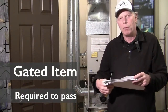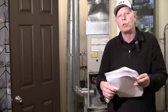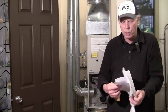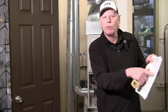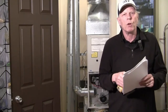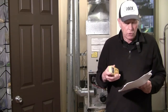But you also need to be able to know where to find the ambient CO levels. Occasionally you'll have CO when you're testing because of the oven, or maybe you had some spillage. So we find the ambient CO levels on our BPI sheet here on the front page. And again, there's 3 levels, 9 to 35, 36 to 69, and 70 or greater. You need to become familiar with these because if you get any ambient CO during the test, you need to be able to respond to that with these standards.